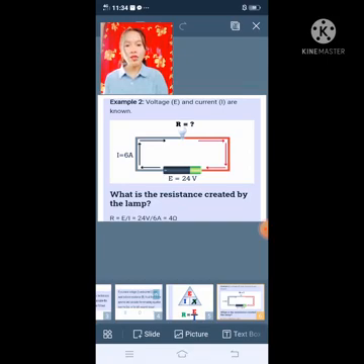So, we have the current of 6 amps and 24 volts. So now, what is our resistance? So, we have here the formula. R is equal to E over I. Resistance is equal to voltage over current. That is equal to 24 volts over 6 amps. So, we have 4. We have 4 ohms resistance now.